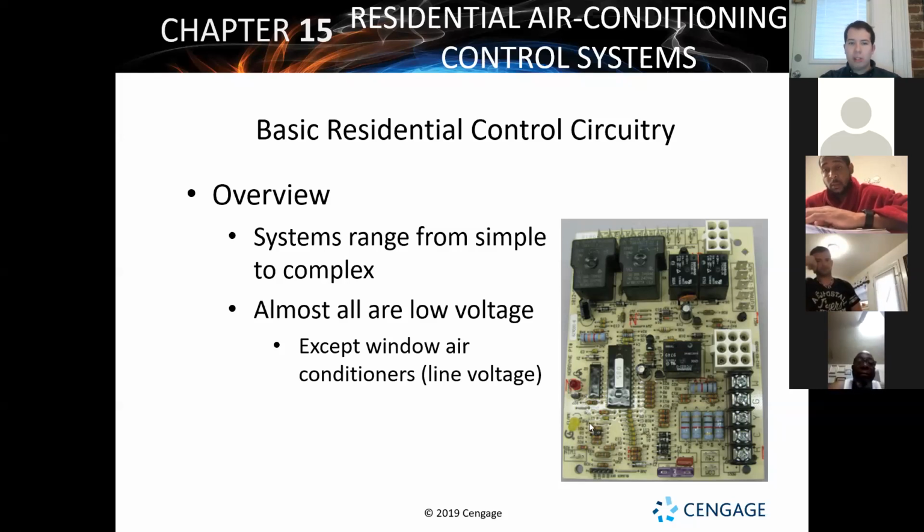The only other thing on this board to look out for, to troubleshoot it, is we'll make sure: are we getting high voltage in? Are we getting low voltage in? Are we getting high voltage sent out? Are we getting low voltage sent out to our different switches and components? The typical connections with the board, as far as troubleshooting, is really just to make sure: is it sending that signal?